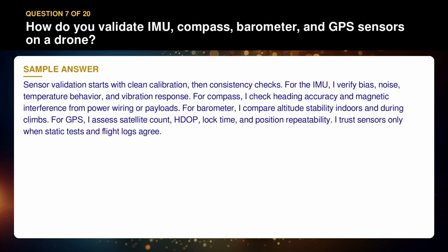For barometer, I compare altitude stability indoors and during climbs. For GPS, I assess satellite count, HDOP, lock time, and position repeatability. I trust sensors only when static tests and flight logs agree.